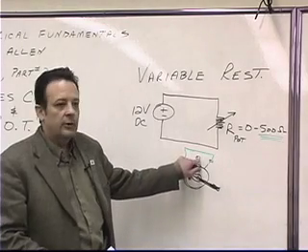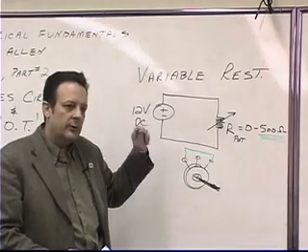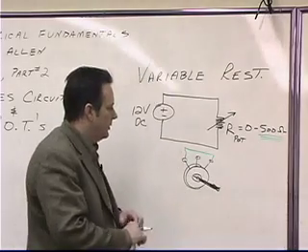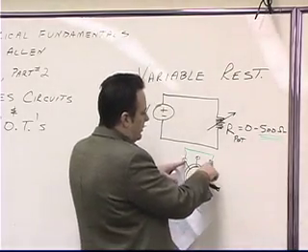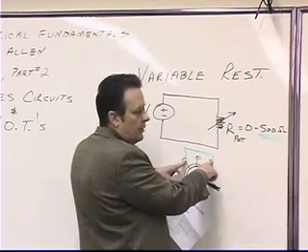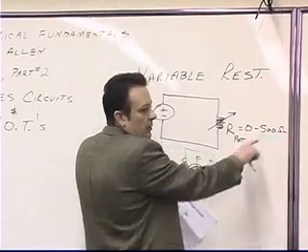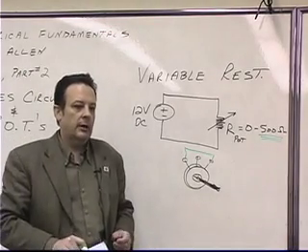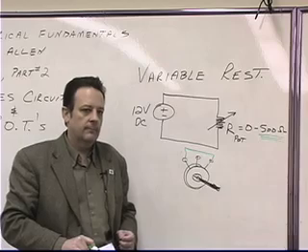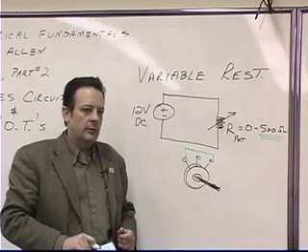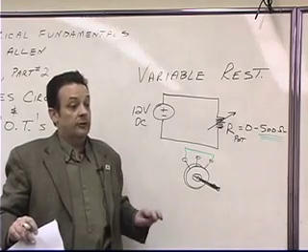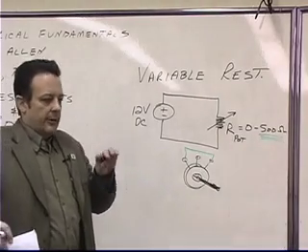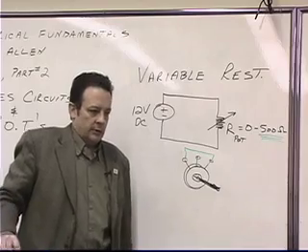Okay, so that's something that you have to experiment with by connecting an ohm meter to the two leads that you're going to use, and then twisting the knob so that you know is it going up or down. What I'm saying is if you connect an ohm meter between the two outermost leads, you're going to get the maximum opposition to current flow that the potentiometer is rated at. Okay? Now that's a little different than how you'd wire it in the circuit. So there is some truth to, if you wired it that way in the circuit, it would short.